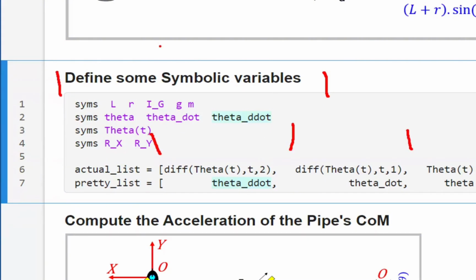And when you do, you should notice over on the left-hand side that you get this blue strip. That gives you some visual feedback that this is the currently selected section. Not only does it give you that feedback, but if you click on that blue strip, it will execute just the MATLAB code that is defined in this section. So I'd like you to do that right now. Click on that blue strip and it will execute the MATLAB code of the currently selected section.